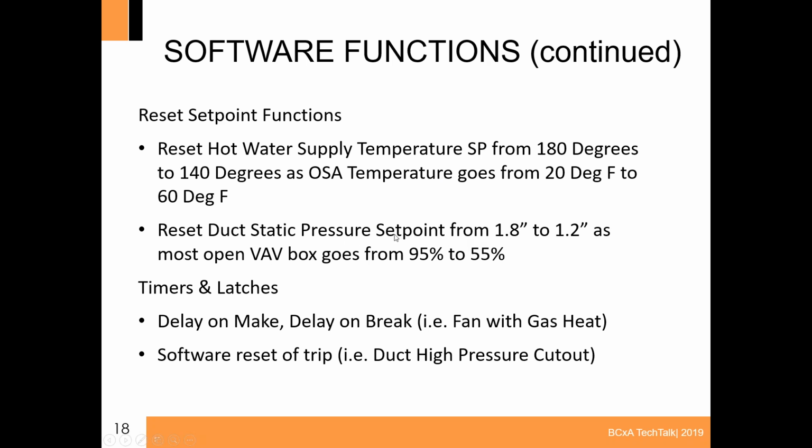Resetting duct static pressure is a new energy saving trend. I guess it's not new anymore. I'm dating myself. But you might reset the duct pressure from 1.8 inches to 1.2 inches as the most open VAV box damper goes from 95 to 55.